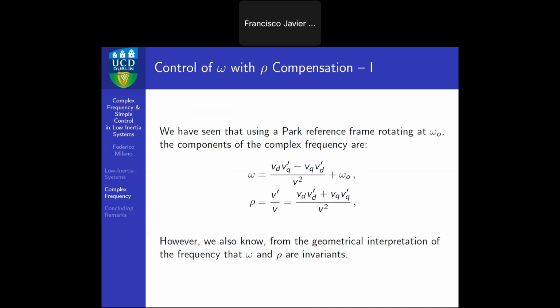So you see there is omega 0. Omega 0 would be the synchronous reference frame. So this would be 314 radians per second at 50 Hz. And this is the deviation with respect to that. This is only local because there is no reference. So we want the voltage just to be constant at the end of the transient.